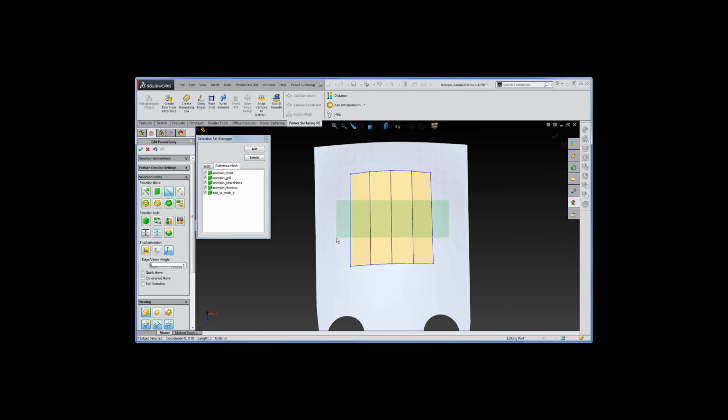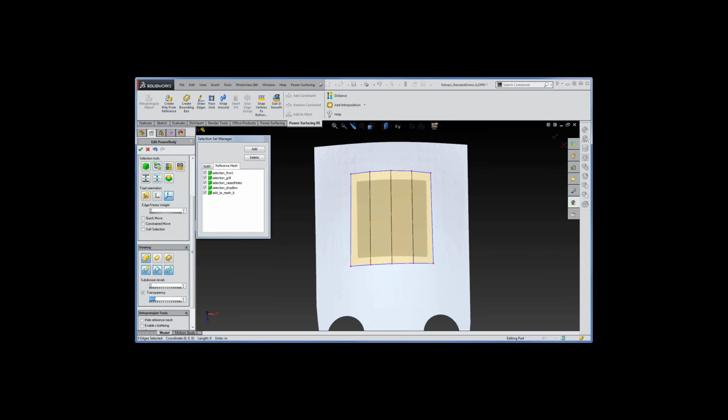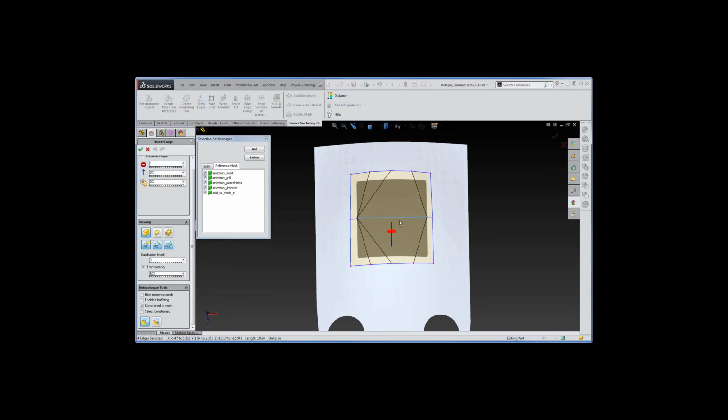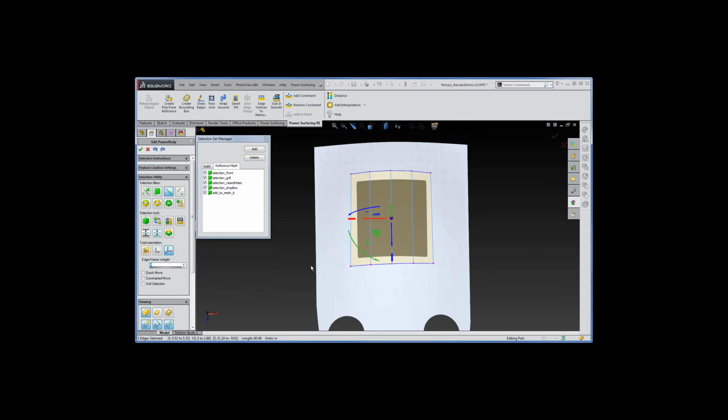but if I try to add loops the other direction, watch what happens. Actually, before I do that, I'm going to turn on the transparency. So now you can see where the hole is. So if I try to add loops going this way, what's going to happen is everybody tries to stick to a surface, because that's what our retopo does. It actually drops our points on the surface. So we need to kind of back up here. So I'll cancel this, undo.